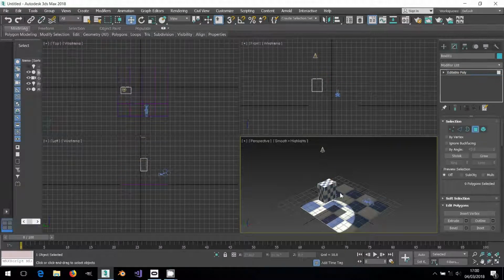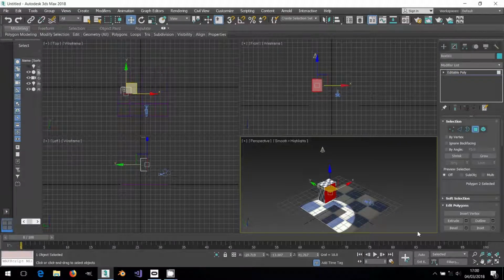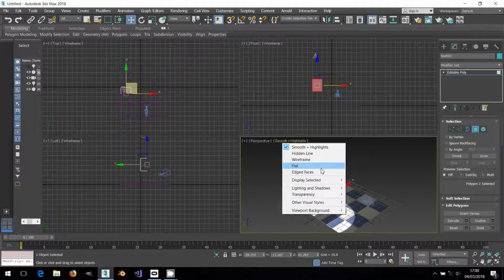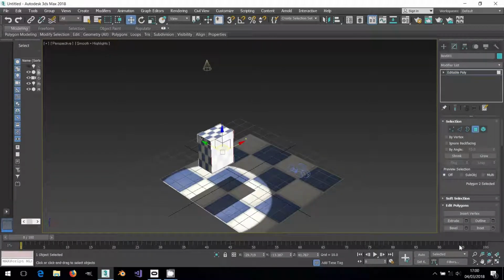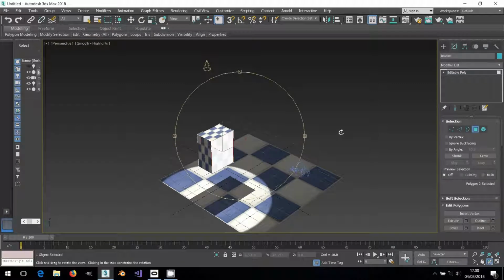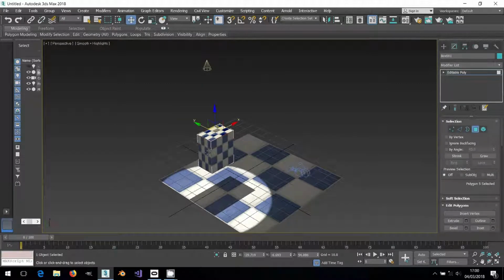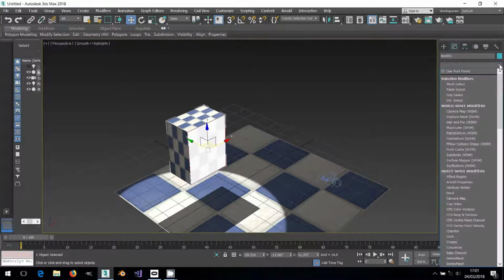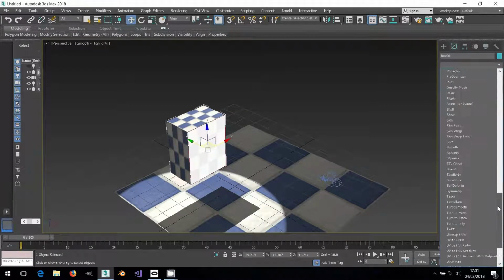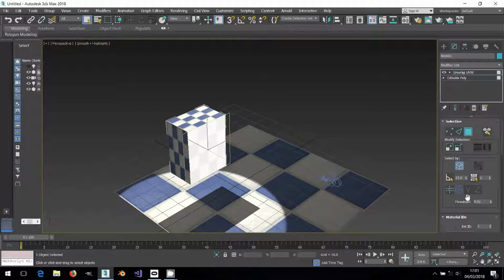Next, we're going to go ahead and make a minor edit to our test geometry. Here you see we've converted that cube into an editable poly. We've just turned off the Max standard face selection mode so we can see Infinity's replacement. As you see here, when faces are selected, we have Infinity's invert face mode showing, so you can see the texture on the geometry.